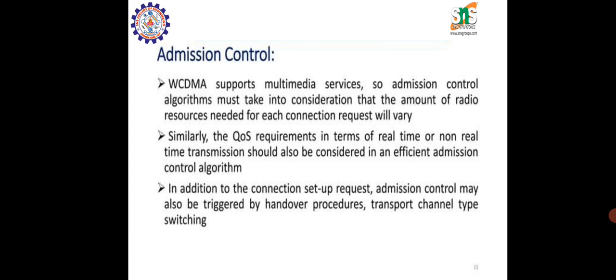Here WCDMA, wideband code division multiple access, supports multimedia services, so the admission control algorithm must take into consideration that the amount of radio resources needed for each connection request will vary. Similarly, the quality of service requirements, in terms of real-time or non-real-time transmission, should also be considered in an effective admission control algorithm. In addition to the connection setup request, admission control may also be triggered by handover procedures and transport channel type switching.